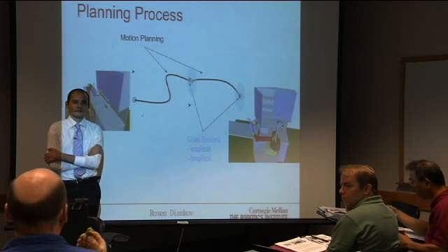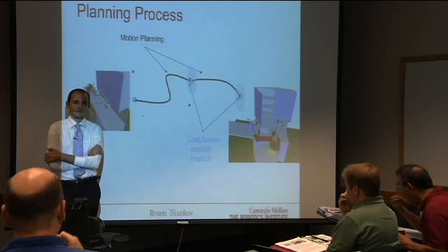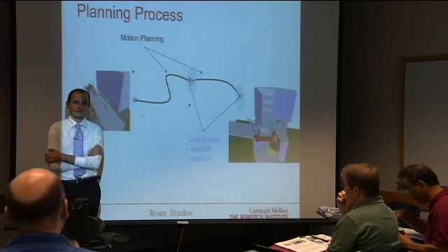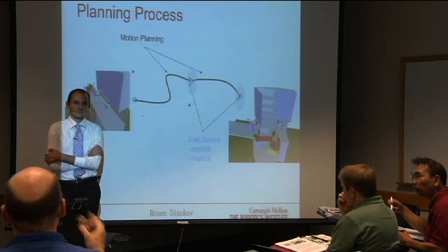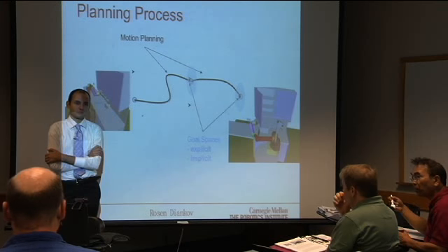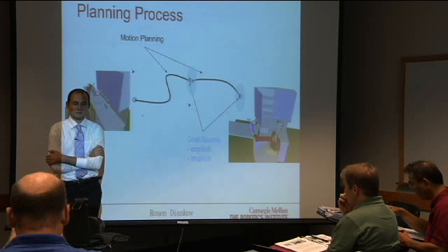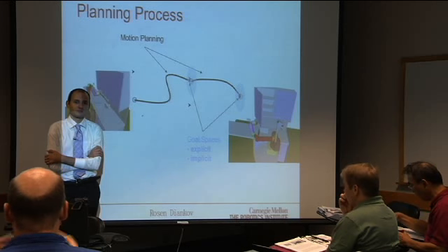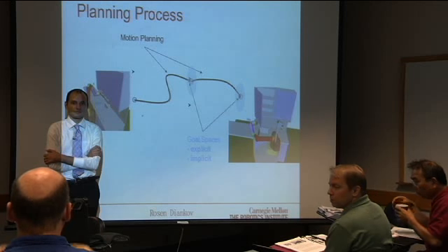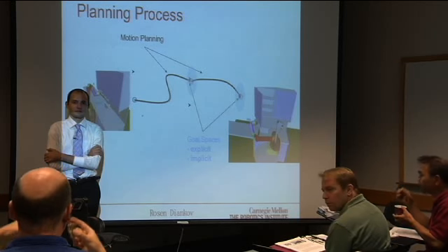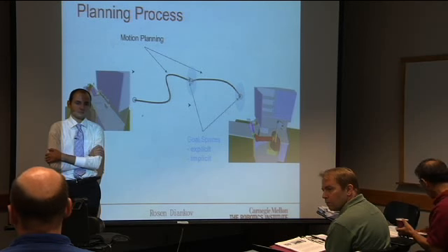But you might want to say something to the effect of, think about the finite state machine architectures for how you program behaviors. You have the current state you're in, approach the object, whatever else. Each state provides the funnel into the next state, such that it provides the initial conditions required for that next state to solve its small, isolated part of the task. Right?